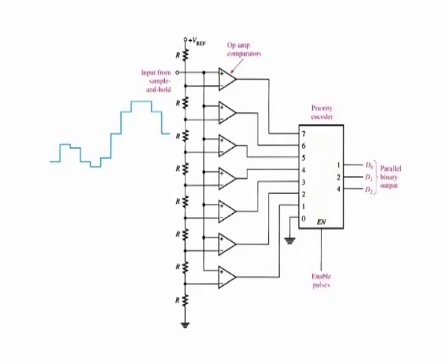The large number of comparators necessary for a reasonable sized binary number is one of the disadvantages of the flash ADC. Its chief advantage is that it provides a fast conversion time because of a high throughput measured in samples per second. The reference voltage for each comparator is set by the resistive voltage divider circuit.